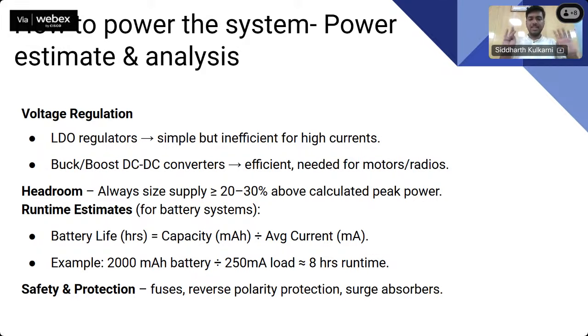So basically, the entire idea is you don't need to have multiple power sources. The first most important thing is, once your components are finalized, you have to take a power analysis of the system. That is, calculate what are the different consumers, that is, what all things will draw power from your power input. Then at what voltage levels each of these work at, and based on that you need to decide whether you want to go with a voltage regulator, a buck converter, etc.